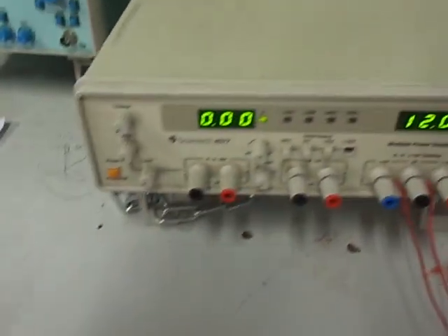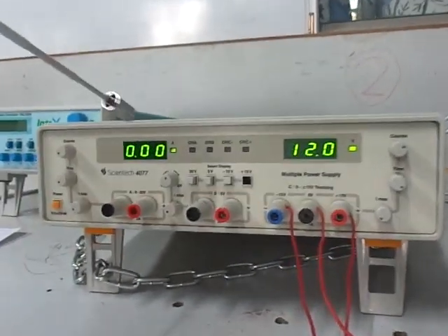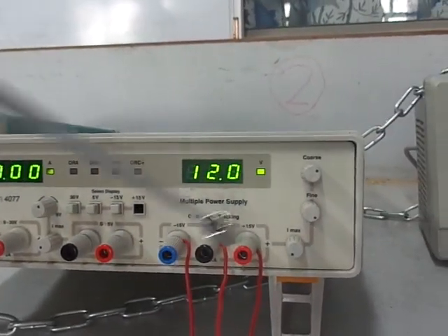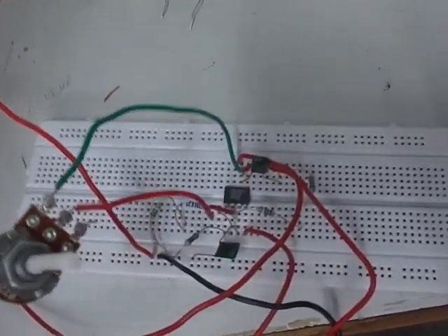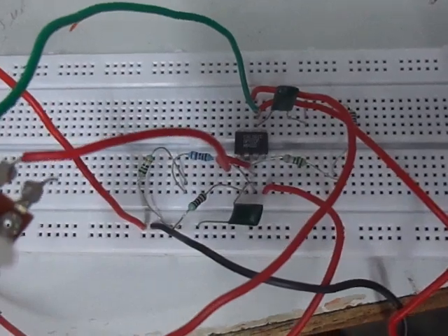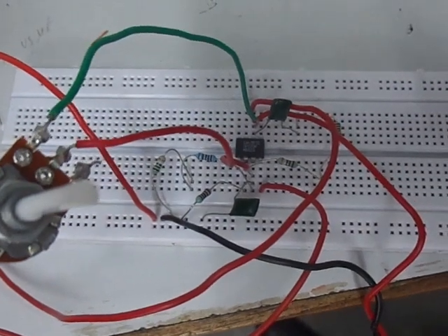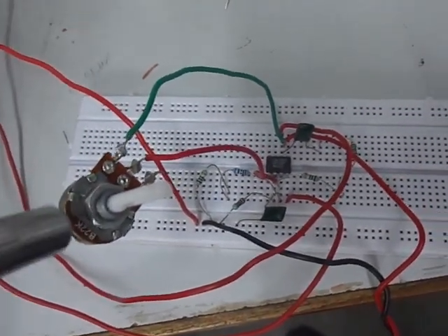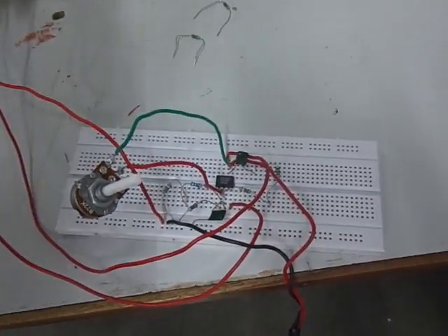Now let us come to the circuit. This is a dual power supply we are going to use. We have applied a plus minus 12 volt power supply. This dual power supply is connected to the operational amplifier, and this is the circuitry where we have connected the series combination of RC, the parallel combination of RC, and the 2 pure resistive elements. As I mentioned, this is the potentiometer of 22 kilo ohm connected in the circuit, and by adjusting it to the proper value of resistance so that the mod of A beta is equal to 1, when this condition is satisfied, we get a sine wave signal generated at the output side.